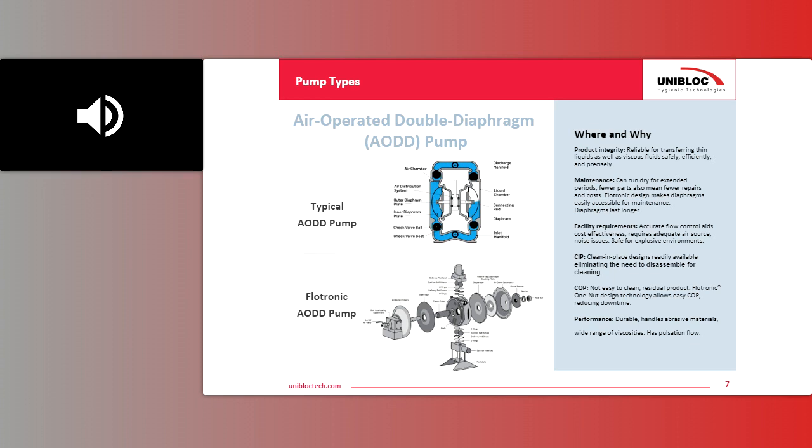I like to commonly call it one of the most forgiving pump technologies. And what we mean by that is it does have run-dry capabilities. It does have the capability to deadhead the pump, and neither of those will damage the pump for more extended periods of time compared to other technologies. It is an air-driven pump, so it also applies to what we call classified areas for explosion-proof, or you're working with volatile chemicals. Then air-driven versus electrically driven aids to that ease of use in those industries. It's much easier to configure that for an explosion-proof or ATEX type environment.